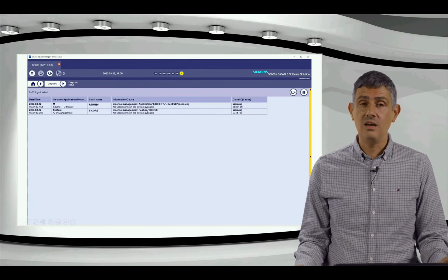This you can do for positions also. So for the positions, you select how the different positions will be displayed in the event list and alarm list. Or for the protection trips, you can also select them. You can select also if for a specific one, the alarm should be assigned when the message is on, or if it is off, like to be inverted. You can do it like that.